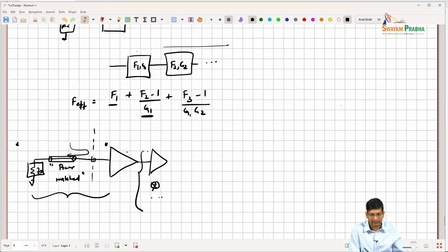But when we design the LNA, usually we design the LNA to be used across applications. We don't know exactly what antenna at what distance people are going to build. So if I don't design this as matched, I might have a situation where I have an extreme mismatch between my antenna and my LNA, and I start rejecting all power. So at least at the input stage, we talk about conjugate matching the LNA. At the output stage, we don't need to really conjugate match the LNA.